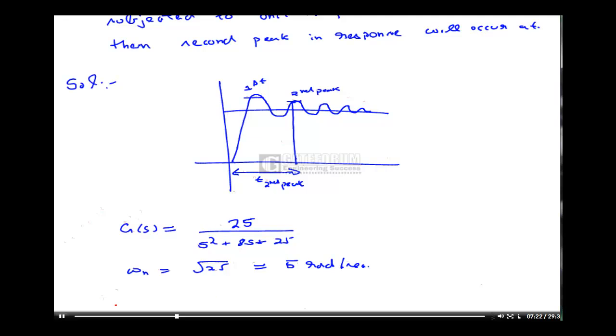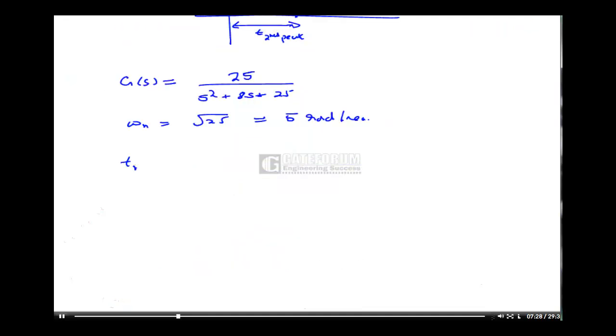Okay. Now the peak overshoot or undershoot happens at t max or min equal to n pi by omega d. Omega d is the damping frequency, where n value 1, 2, 3 decides the minima or maxima.